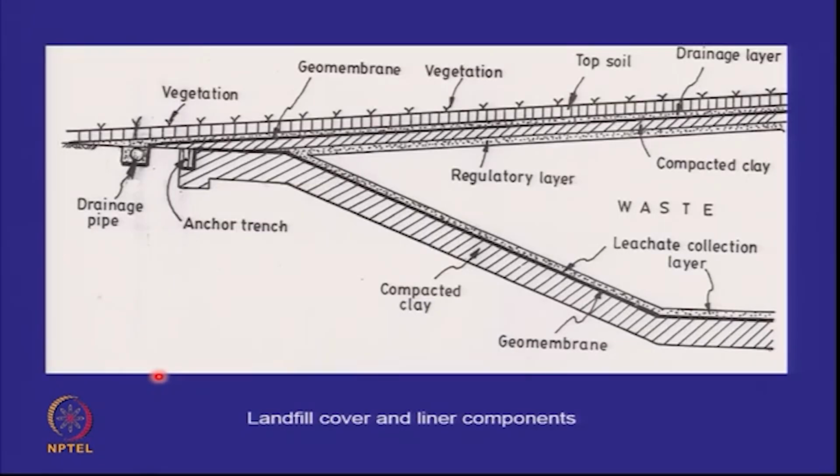And let's go back to this diagram which we have been working with. We've talked about liner, we've talked about cover, and today we are going to talk about that if you have infiltration and if your barriers don't work, some water will come down, or if this is a perfect barrier, the waste itself may be wet, and as you build up the waste, it will squeeze the pore liquid out.